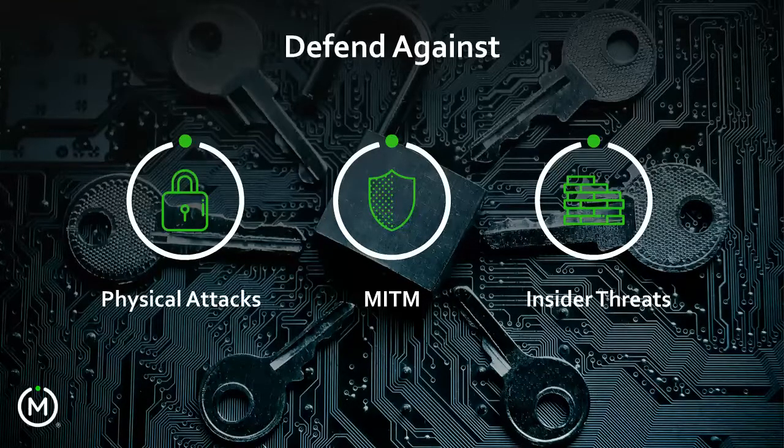Well, there are two ways. One way is to use the flash memory with some kind of policy-based access to store keys and certificates. You take a data flash portion of the flash and, with some kind of policy authorization, have the ability to store keys and certs in a data flash. And that would require some kind of device fingerprinting to protect it with some symmetric key.